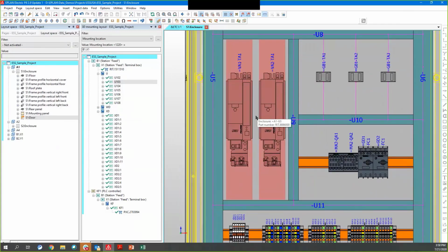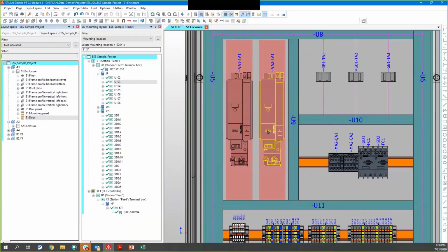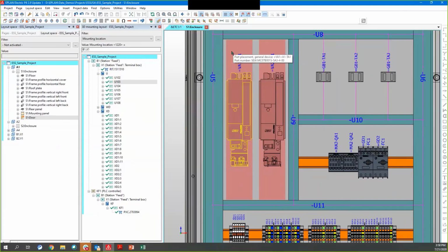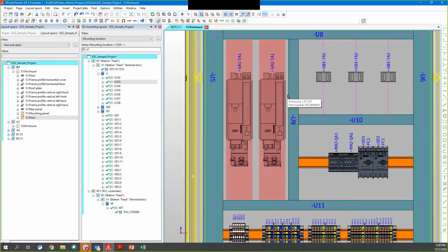And that clearance comes direct from the part. This part comes from a manufacturer and is downloaded from the data portal. So this information isn't just randomly something we've typed in. This is what the manufacturer has said is the appropriate clearance for this device. And if I made it such that something was in the way, either another component or the duct work, that error checking would identify that. I'll turn that clearances off.